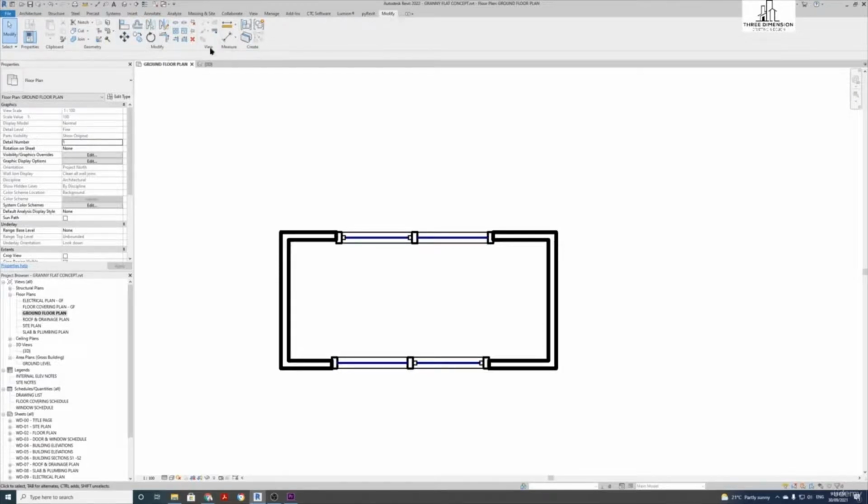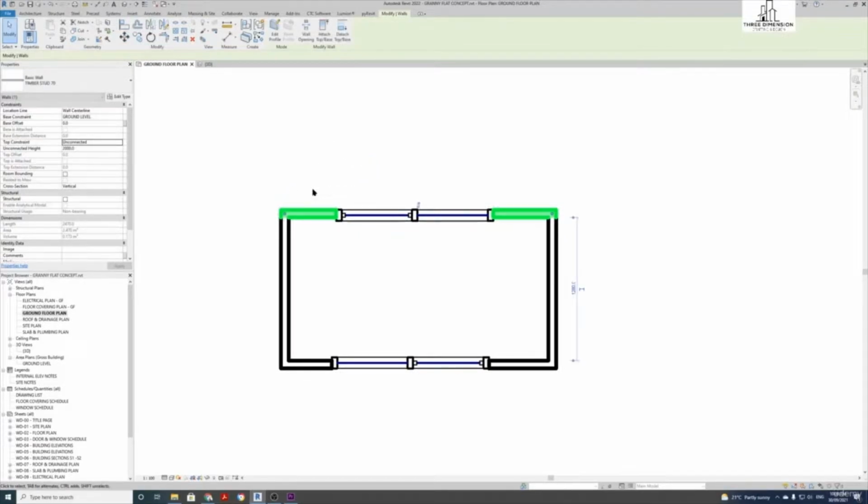If you click the modify tab and come to move, we click on that, come down here, we can select an item, select your wall, click enter. Now you can click again and move in the direction you want to move this item. You can either move it and just click, or you can actually type in a distance. So you can come down your keyboard here and type in 200, click enter, and that'll move your wall across by 200.